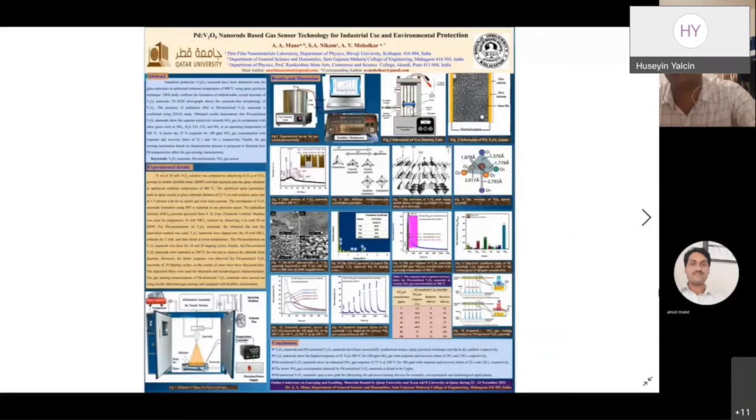The nanorods are densely grown with uniform length and similar shape. Small pores of varying sizes are also observed due to random orientation of nanorods over the surface of the film, which provides a larger contact area and thereby more adsorption sites for gas adsorption.